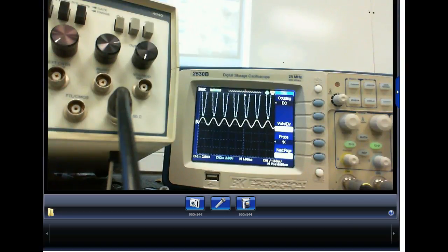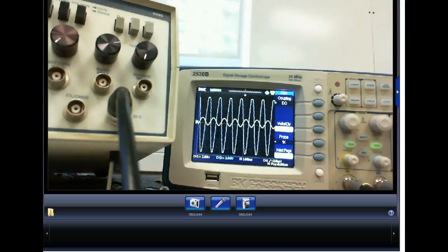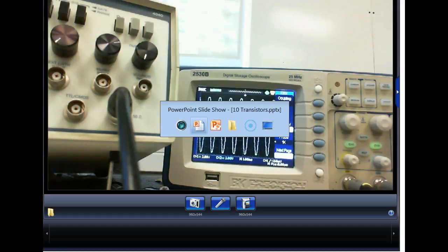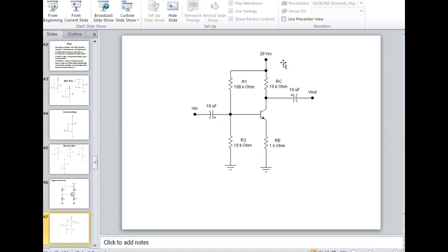So here we have the AC, and then here we have AC across our load. So that's what that's for. We call those coupling capacitors. So these capacitors have names, and you can see how they got that name, right? Because they allow input to couple into the amplifier.